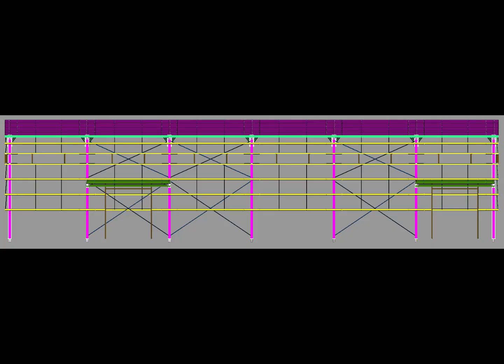However, one important engineering point should always be remembered. The exact function, size, spacing, and connection of a sag rod must be taken from the project design and applicable detailing information. We should not determine these values simply by looking at a 3D model. The 3D model is excellent for understanding geometry and location. The engineering drawing and design information are required for the actual member specification and connection detailing. This distinction is very important for professional detailing work.